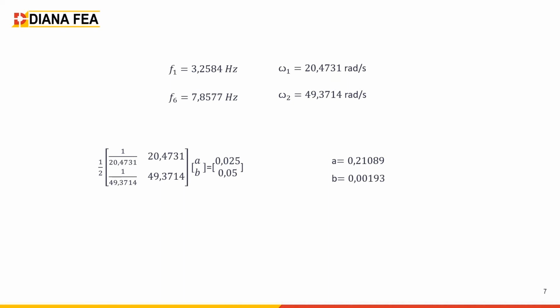So we did that by hand calculation. First we perform an eigenvalue analysis, and from this eigenvalue analysis, we identify the two frequencies that we are going to use. We also play a little bit with the damping ratio to make sure that we are not damping out too much based on our earthquake signal. But these parameters can actually be derived directly by Diana from the eigenvalue analysis. And that's what I'm going to show you, how to activate that.